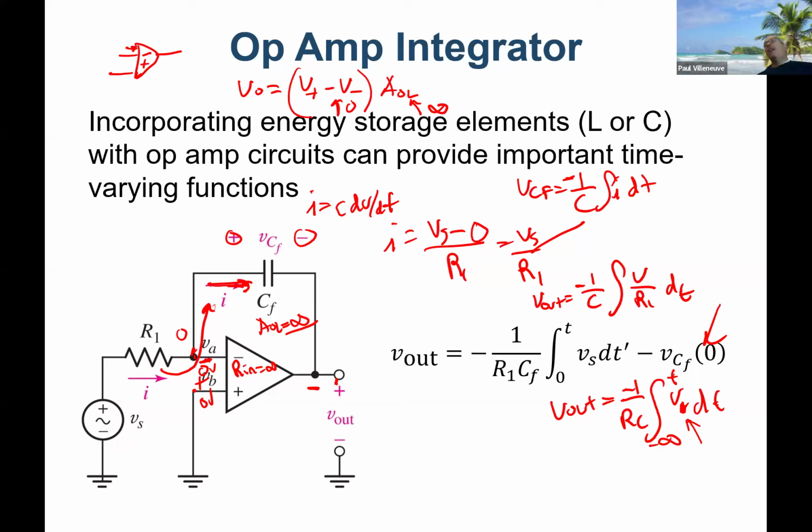In the real world, op amps have greater than 1 mega ohm of internal impedance or equivalent internal impedance, and the gains are like 200K, 500,000, really big numbers. So we approximate real world op amps using ideal conditions just to make the work a little easier to understand.